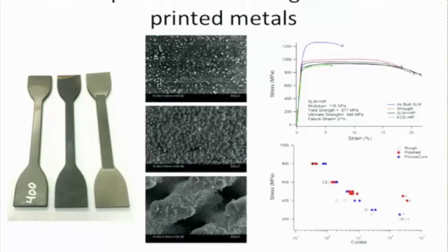The other big thing that you worry about with a 3D printed metal is, if you print the metal, does it have the same fatigue properties, which is something in the application that really is critical long-term. And so this is early data on stress life curve for the 3D printed metals. And obviously, as you add these features, their life goes down. So you pay a price. You can 3D print complex features and shapes, but then you start to lose some fatigue performance. And so that was the research we were doing.